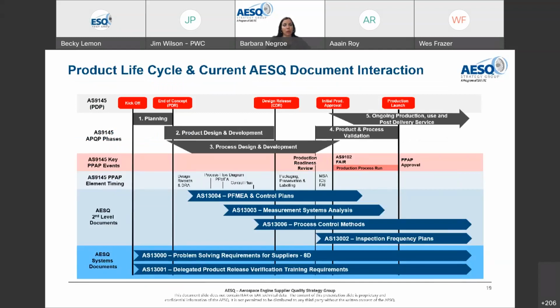You can see that, from an evolution standpoint, we first created individual specs and then commonized them. So we started out with various specs like AS13004, so PFMEA and control plans, MSA, process control methods, inspection frequency plans with AS13002. And really each of those needed to happen as a journey to a single common specification for 13100. If we hadn't done it that way and taken incremental steps along the way, it would have been a lot more difficult to pull these into an overarching specification.